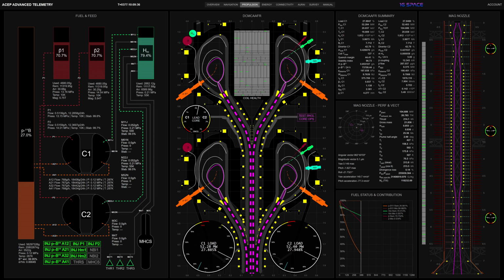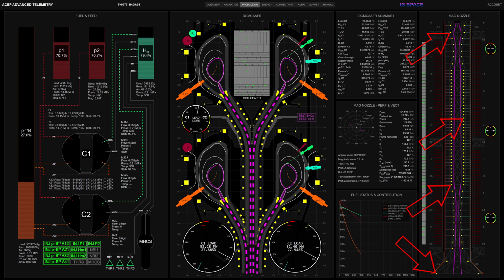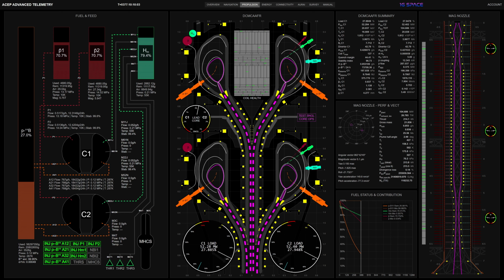Vectoring effects are visible as controlled asymmetry in the plasma path. Small, symmetric deviations correspond to routine attitude control, while sustained asymmetry reflects deliberate thrust steering at the cost of increased divergence and localized thermal stress. Surrounding coil structures represent the magnetic elements responsible for confinement, compression, trimming, and vector control. Their arrangement defines the effective expansion ratio and the achievable range of thrust vector deflection.